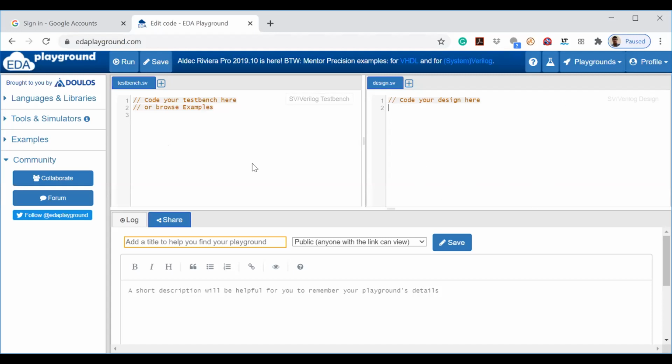And the purpose of the test bench window is to test your design, whether your design is working properly or not. Suppose you have already coded the design and it is running, but whether you are getting proper output or not. In a digital system, generally we put the input in digital form. You know how to verify a logic gate by checking its truth table, 00, 01, 10, 11, etc. In a test bench window, we shall do the same thing.